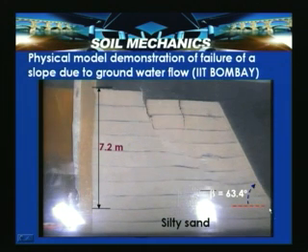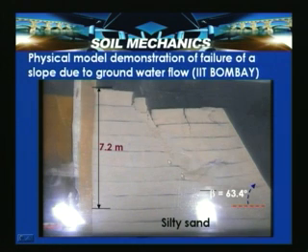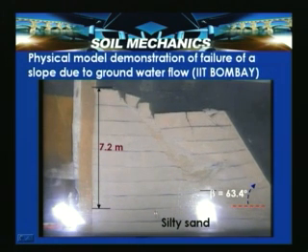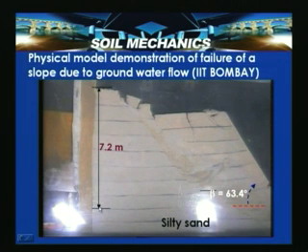As the water reaches the toe, you can see that the slope attains failure. This is the formation of tension cracks. This soil is equivalent to a silty sand, with a height equivalent to 7.2 meters, constructed with moist compacted silty sand, and the slope has an inclination of 63.4 degrees. So, let us look into the details again.